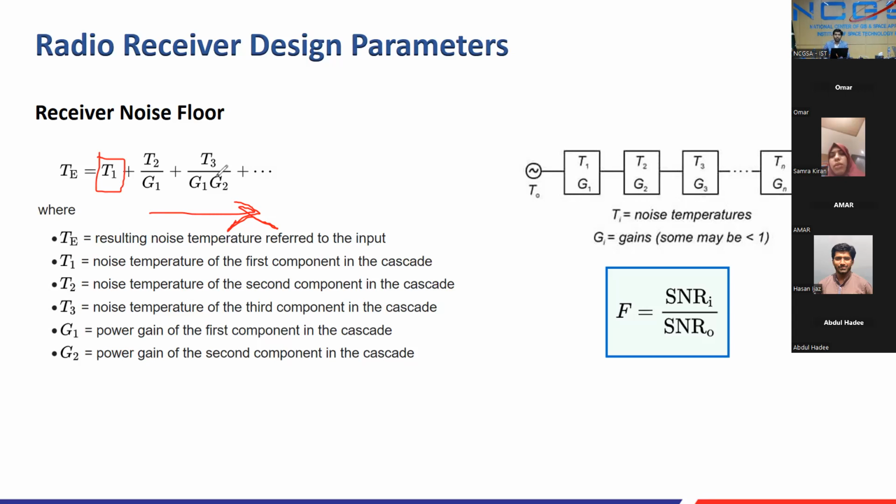Now, there's another parameter known as noise factor. Noise factor is the ratio of input SNR to output SNR. Noise factor is, I think, linear. You take the log of that and it becomes the noise figure. As RF engineers, I think most people already know that.